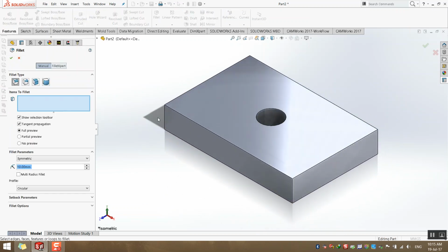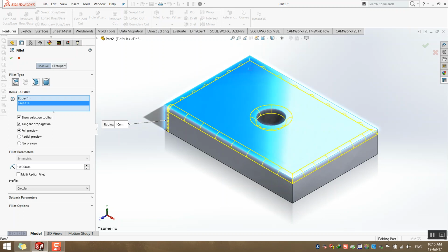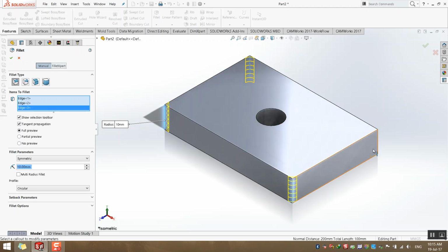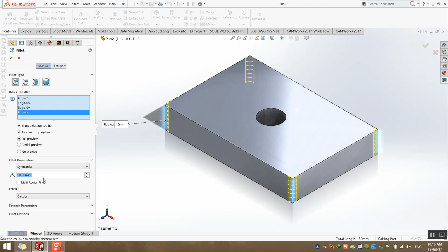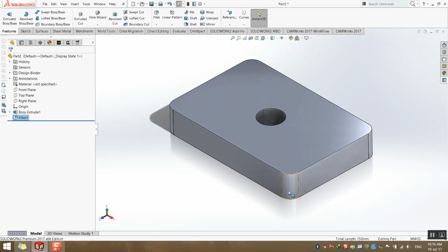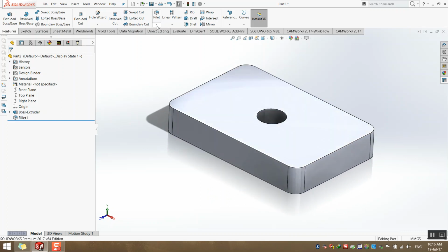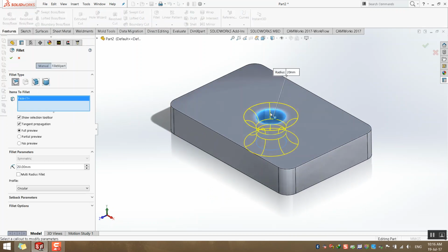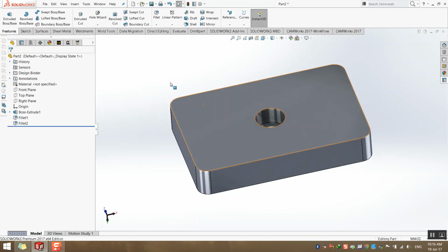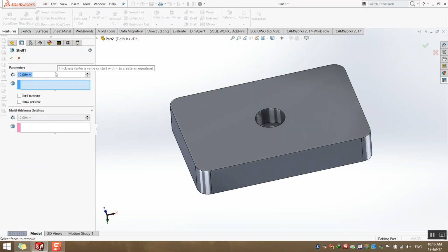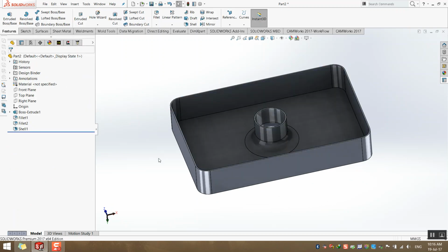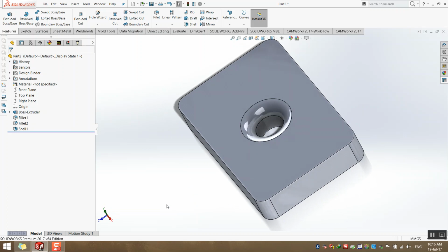Quick and easy. You can fillet corners with a specific number you need, radius 20. Also you can do that. And finally you can add a wall thickness of 2 millimeters and do that. This model has been created in minutes, or in seconds if you are quick.